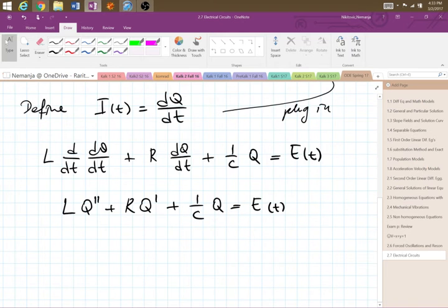Now we're just going to recast this into a current, because most of the time what we are worrying about is what is the current. The reason is you can have wires just as thick. The more current requirements, the thicker the wire. That's why you shouldn't be swapping your 15 amp fuses with 20 amp fuses, because your wires in the wall are still 15 rated. The more current, the more heat, so on. So these things have to all grow proportionally in order for us to have this equation.